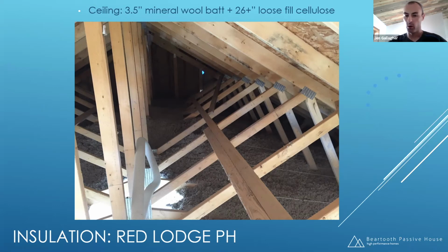So we went with mineral wool because we liked the thermal properties of it. We liked the sound properties of it. We liked the moisture properties of it, the vapor permeability. And it was a prepackaged product that we could buy from Lowe's and have them deliver it to us, and we just installed it. So that's why we went with mineral wool.